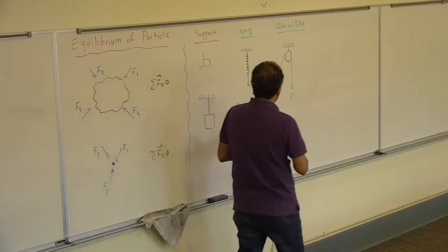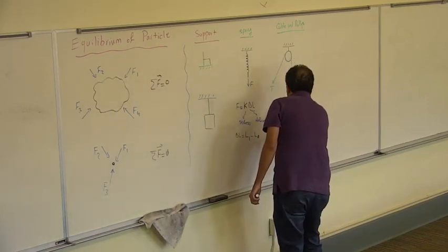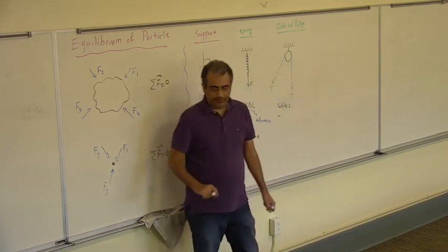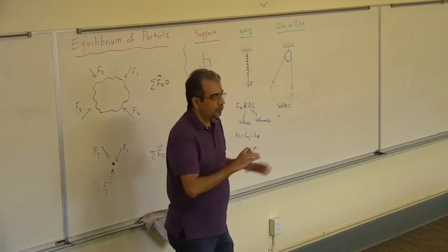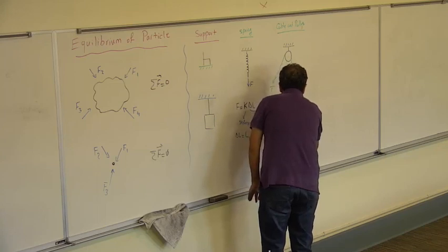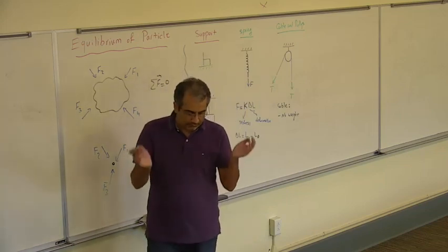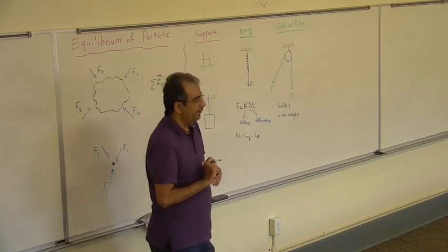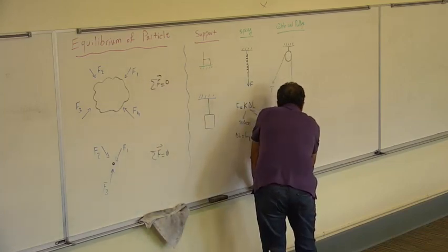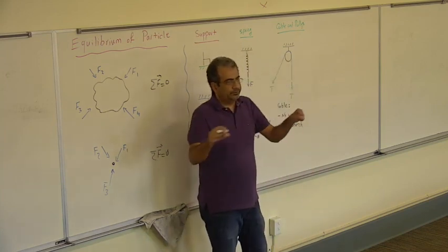For the cables, there are four conditions that you have to consider. The first condition is that the cable has no weight. The cable does not have any weight, so in analysis we do not consider that. The cable cannot stretch, so it's not flexible.